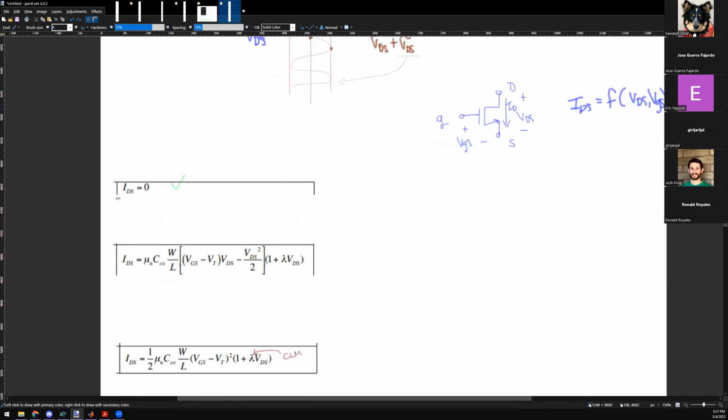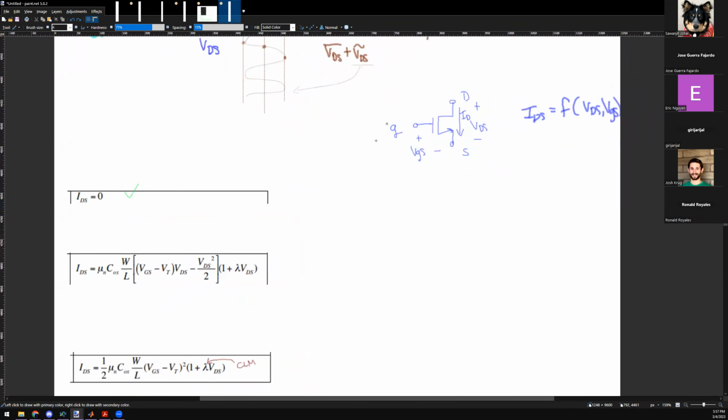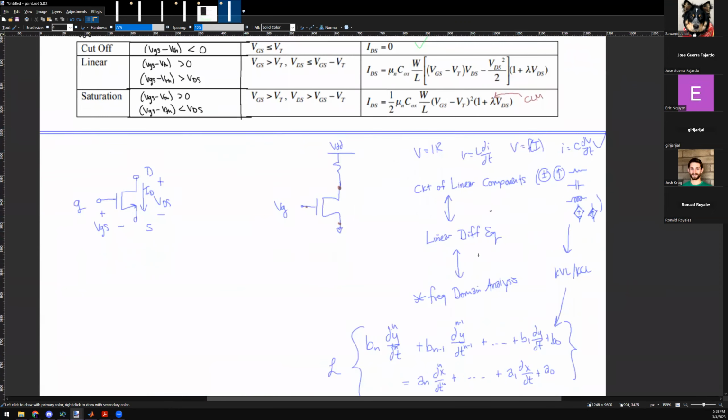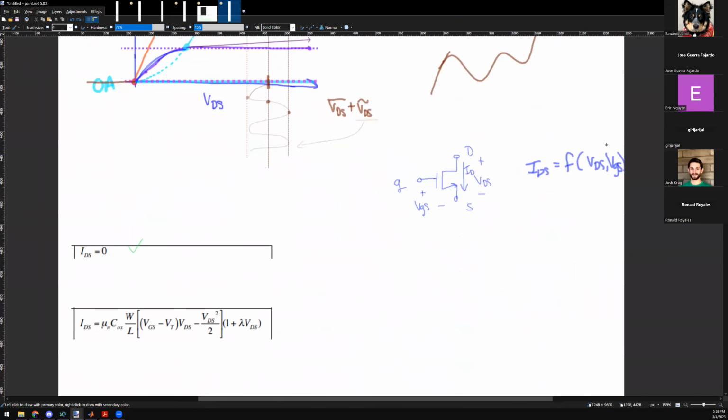Okay. So for each mode of operation, I could define the following. I'm trying to decompose this guy into this. And I have two options. What are the two derivatives I can measure? IDS and VDS? Okay, IDS to VDS, right? Good. What else can I take a derivative of? IDS, VGS. Correct. And those are your only options, right?